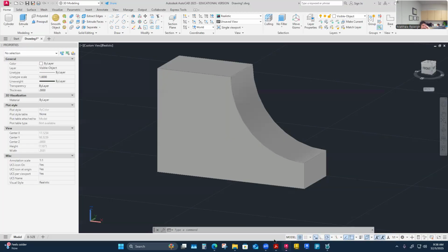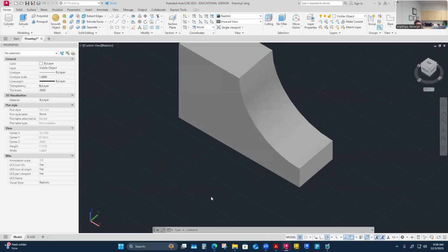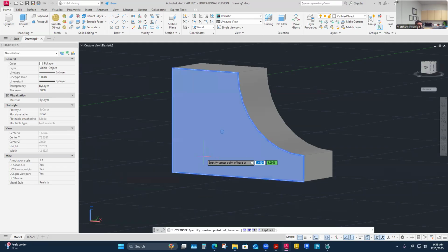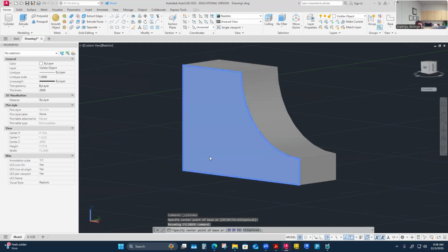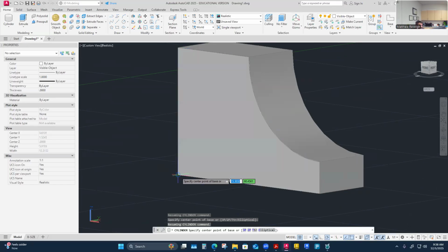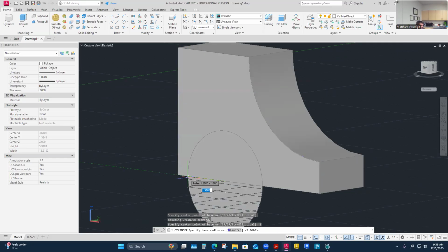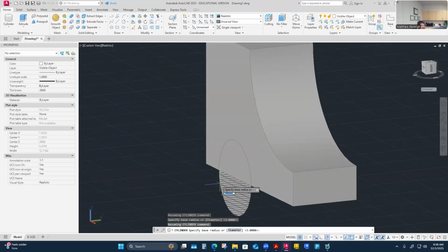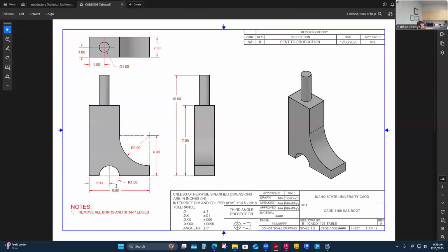So let me come back to my shape, and let me pick cylinder. I think if I want it to be cutting through this way, I'm going to reference this surface here and then highlight over this for a minute. I'm going to reference that surface, highlight, and pull away. I think I can pull away along that surface. Was it 2 inches or three? I can't remember. And that just cursored me over 2 inches. I'll do that again, but I'll make sure that it is two. Yeah, it's 2 inches over to the center of this, and it's on that bottom edge plane there.